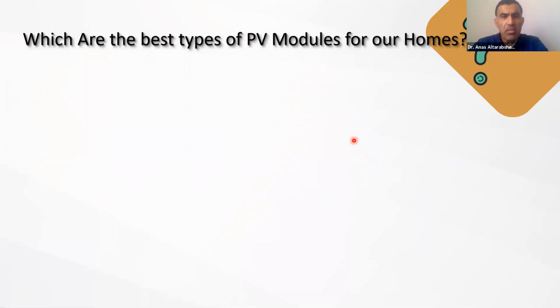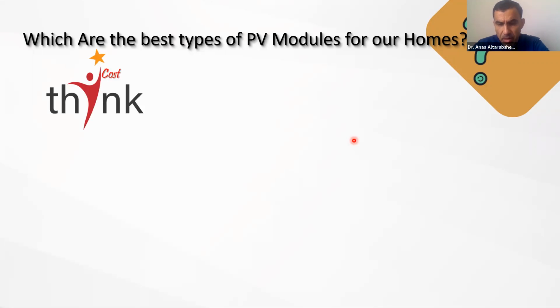Okay. Now you may ask yourself right now, what is the best type of PV modules for our homes? While asking ourselves this question, first of all, we have to think about the parameters by which we will select. First of all, the cost of the technology or the cost of the PV module. The second figure of merit is the output power. The third figure of merit is the space. I mean here, does the available space on our roof accommodate the whole number of modules?